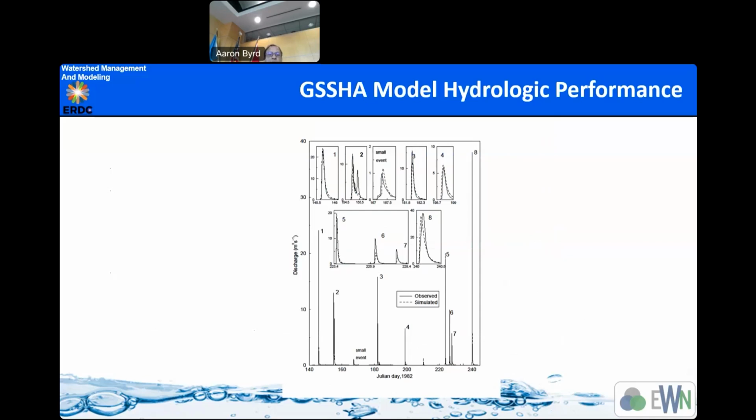Actually, this is hydrology. Now, why is hydrology important rather than sediment? You don't calibrate sediment itself first. The first place is you calibrate hydrology. You have the hydrology right, then you go to sediment. Otherwise, you are just getting the right answer for the wrong reason. Right? So the steps are: first make the hydrology right, then go to the effect of hydrology. That's erosion.